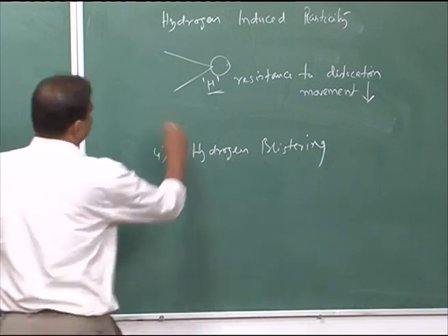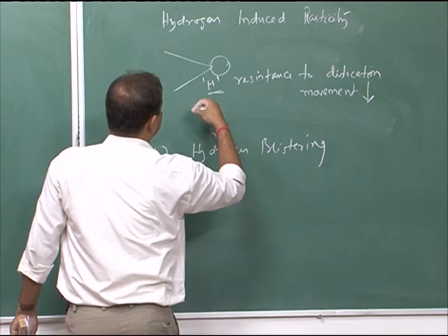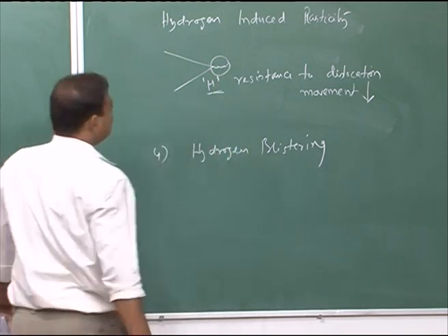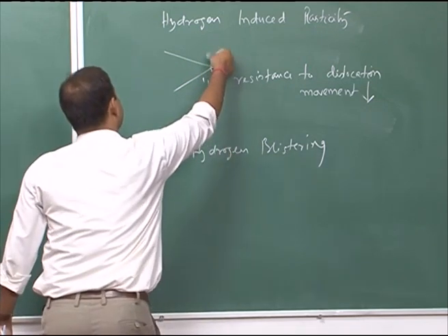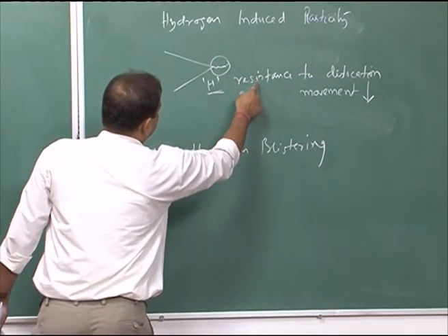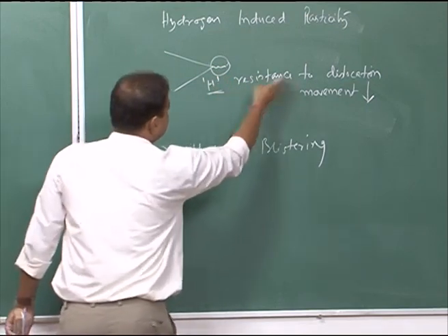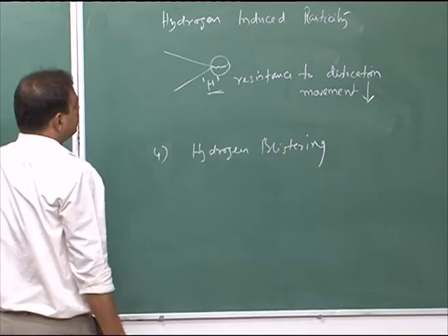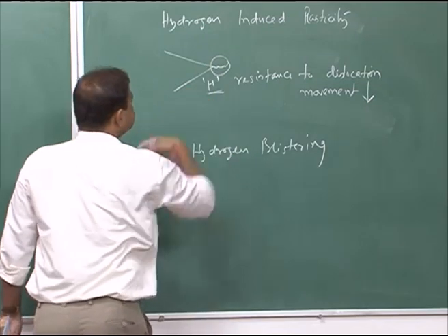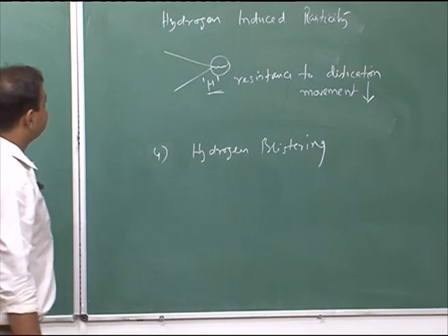So, this zone of the crack can be deformed, and the crack can propagate. Once it deforms, strain hardening can happen, but actually hydrogen reduces the dislocation movement. So, the strain hardening effect would be much less, and the crack can propagate easily.